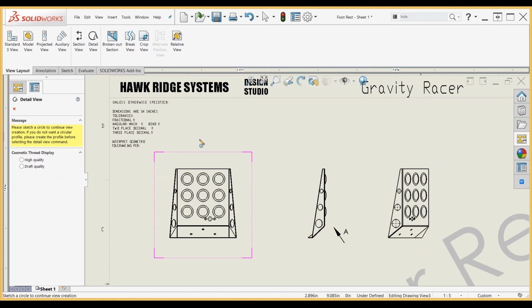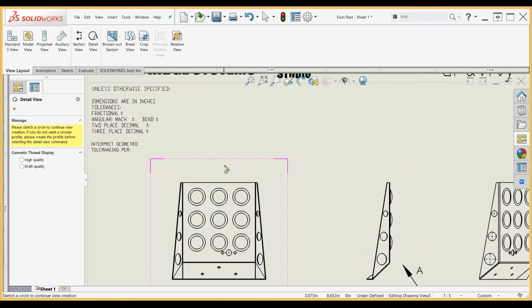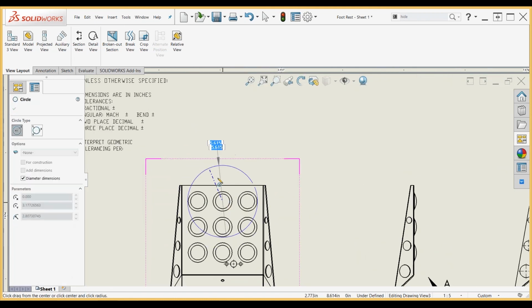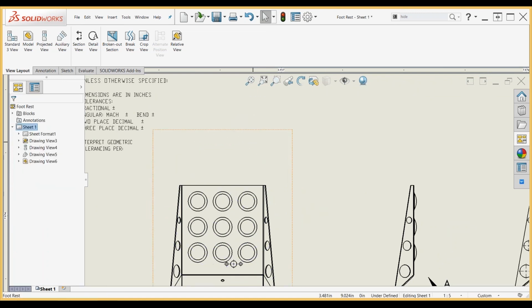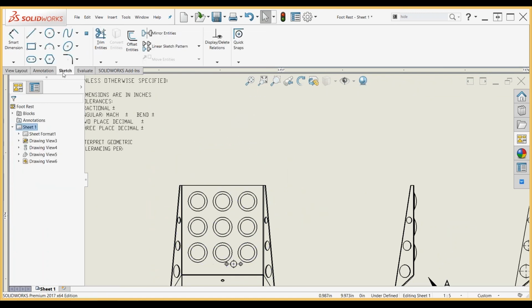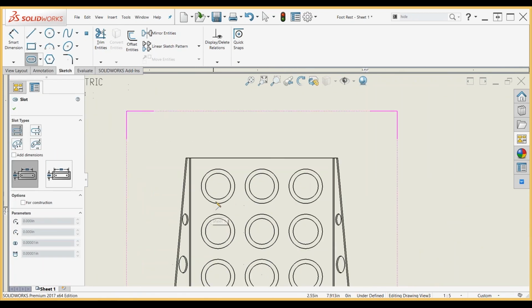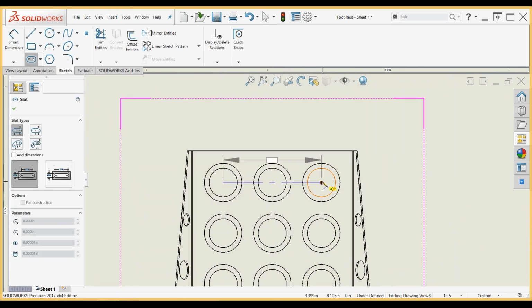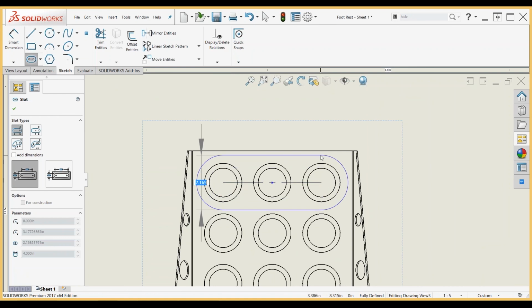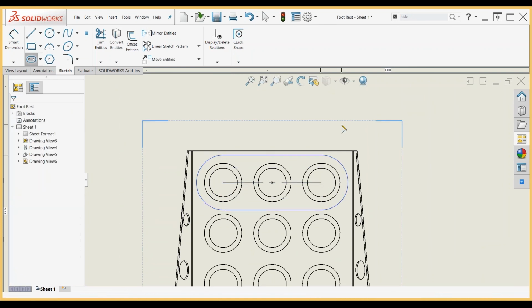Location labels can be used to help pinpoint the location of where that B actually is. So I'm going to click on my location label, and I'm going to click on the B itself, and it's going to show me, okay, the view B is on sheet 1. As we can see, our upper text references the sheet, and it is in zone D6.